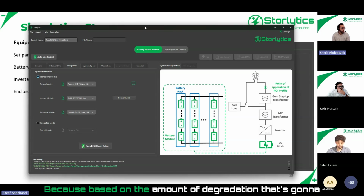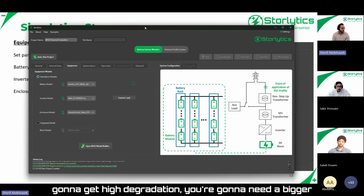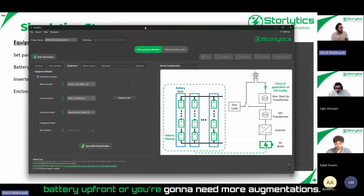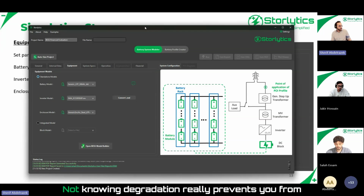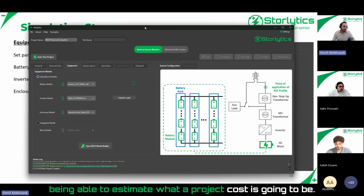Because based on the amount of degradation that's going to happen, the cost of the system changes, because if you're going to get high degradation, you're going to need a bigger battery up front, or you're going to need more augmentations, and batteries are not cheap, they're expensive. Not knowing degradation really prevents you from being able to estimate what a project cost is going to be.